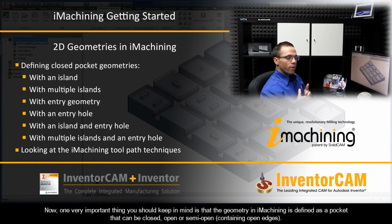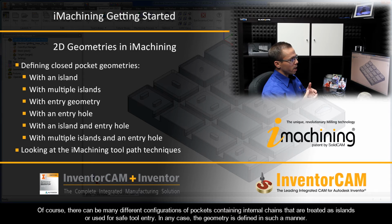Now, one very important thing that you should keep in mind is that the geometry in iMachining is defined as a pocket that can be closed, open, or semi-open, meaning containing open edges. Of course, there can be many different configurations of pockets, containing internal chains that are treated as islands or used for safe tool entry. In any case, though, the geometry is defined in such a manner.